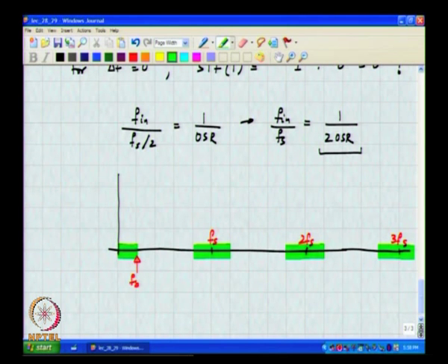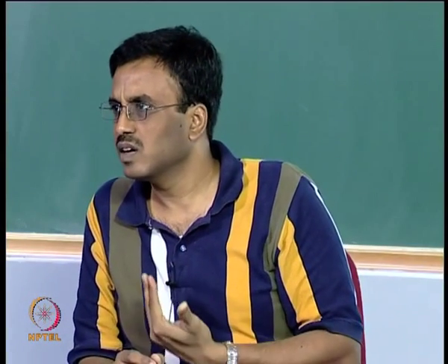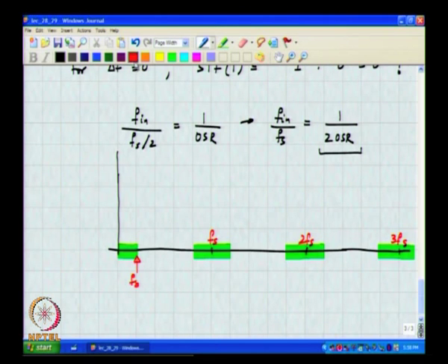alright. The STF at DC is, what is the STF at DC? 1, and at low frequencies you can expect it to be close to 1, correct. So, at DC or in the signal band the STF is close to 1. At Fs, what is the STF? At multiples of Fs it is 0, at frequencies close to Fs it is close to 0, right.